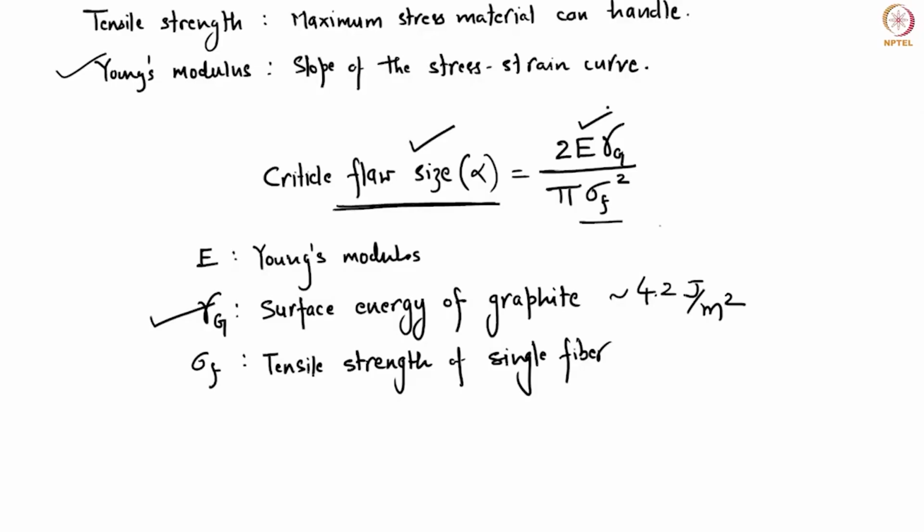What does that mean? That means that if you increase your pyrolysis temperature and you get a Young's modulus that is very high, you may actually also get larger voids in it. This relationship may not be valid for ultra thin fibers, because there you have defects annealing out very easily. However, if you have 1 micrometer to 5 micrometer diameter fibers, which is often the case with industrial carbon fibers, indeed you may get some defects when you increase the carbonization temperature.